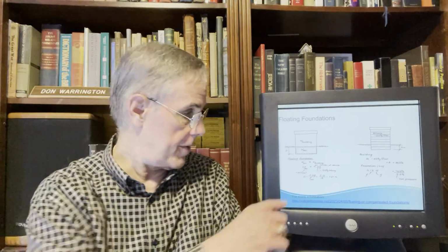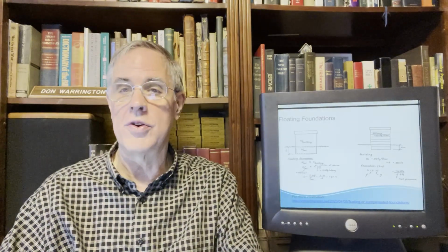So what he does is he multiplies all that through and solves for D, which is equal to N, which is a 3-story building in this particular case, times the delta Q, which is 10, over his unit weight in kilonewtons per cubic meter, which is 18, and he gets a depth of 1.67 meters.